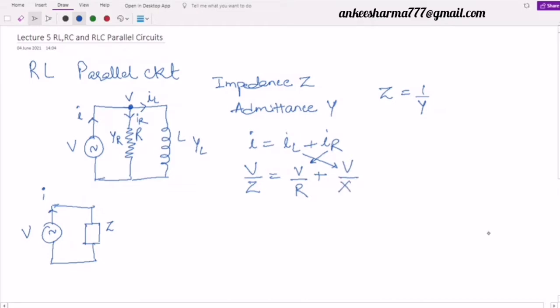That is, you know, the impedance of an inductor is XL. But we have studied that whenever we are discussing only a single inductor, there is a phase difference between the voltage and the current, and that phase difference is equal to plus 90 degrees or minus 90 degrees. Can anybody tell me? In the case of an inductor, our voltage leads but the current lags the voltage source. It means whenever we are considering the current, it should be minus 90 degrees. Now the same can be represented as, look here, the V is constant everywhere.